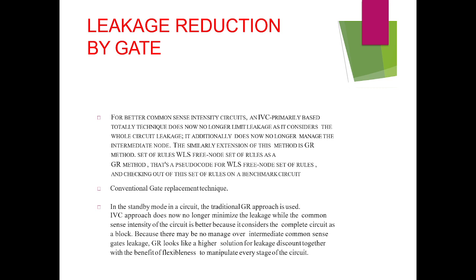As we can see, we'll be using the conventional gate replacement technique, and in standby mode of the circuit the traditional GR approach is used. Also, an important point is that the IVC approach does not minimize the leakage as well when the logic depth of the circuit is larger, because it considers the whole circuit as a block.